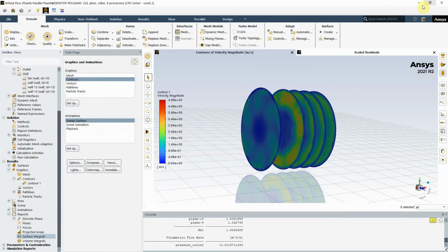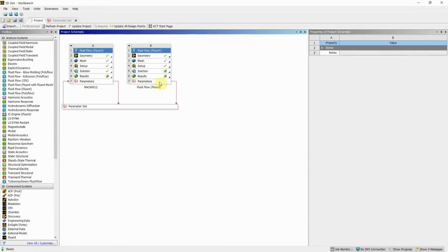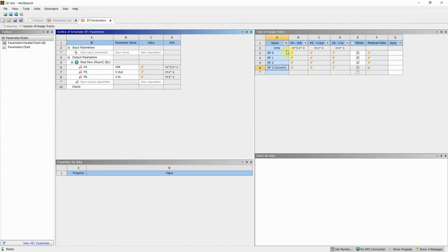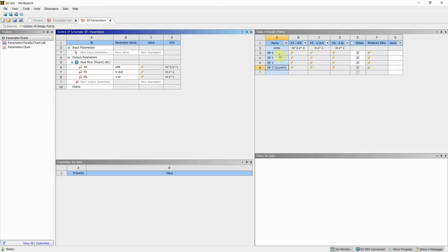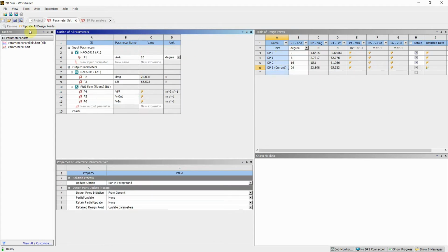And that way you can do a parametric study in ANSYS here with, for example, different... I haven't made the blade installation angle into a parametric function, but you can change that by just going in there, clicking on that box, and it'll change it into a parametric function in DesignModeler. Then you can get the volumetric flow rate out, and you can start doing a comparison study of your blade installation angle against how much volumetric flow rate is flowing through, what makes it better, what doesn't make it better, how much velocity is going in and how much velocity is coming out. Now, what I want obviously is, as you can see here, it's just done that because I've copied the parameters.